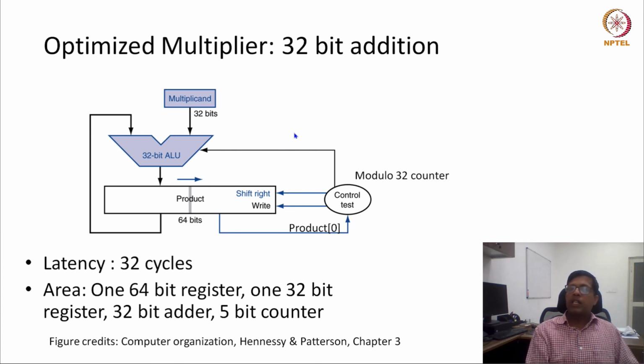Pipelining optimization can only be possible whenever resources are free, for example here we have at least utilized these resources. The product register has been multiplexed, it is doing both operations, it is keeping the multiplier as well as keeping the result. So this way we are trying to have some optimization. Okay, so with this motivation in mind, let's look at the other design also, how a division would be done.